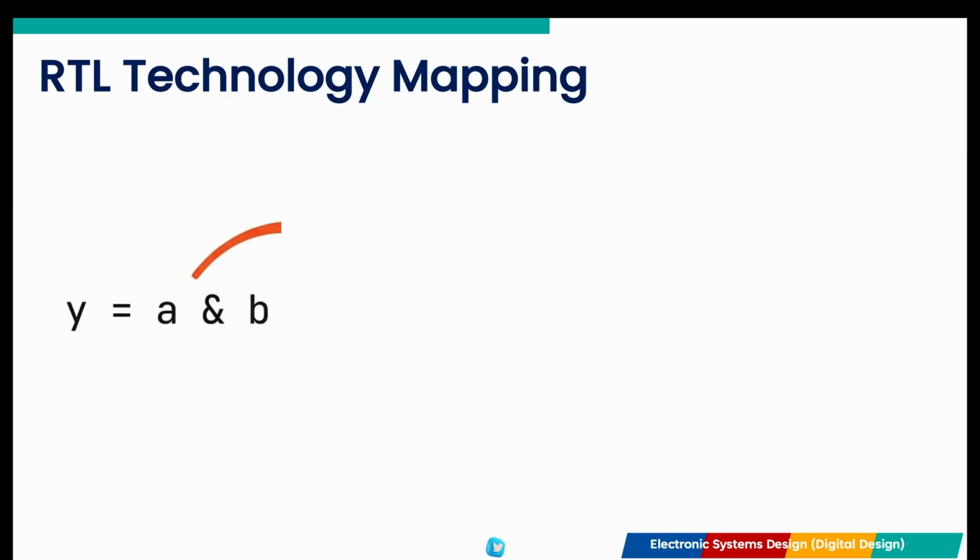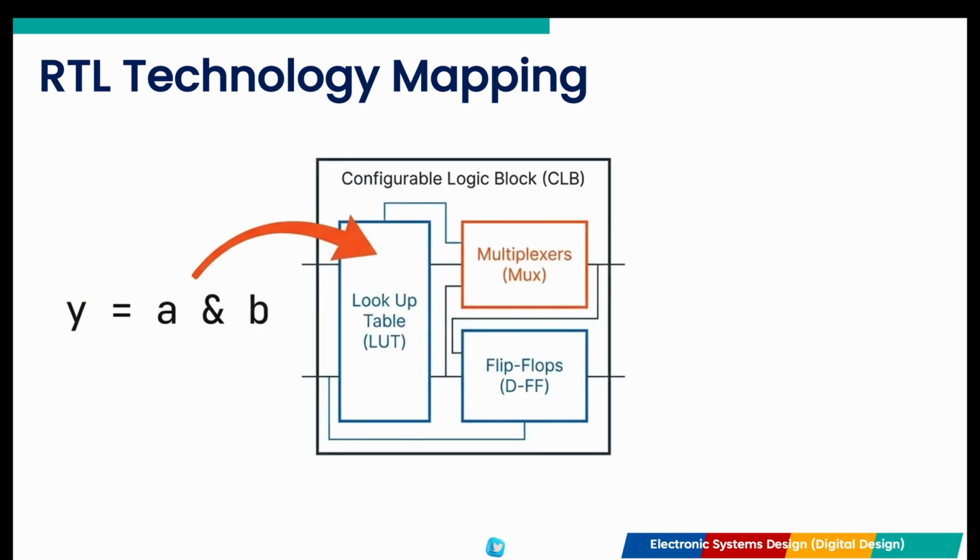Now that the logic is as small as possible, we move into technology mapping. A generic AND gate doesn't exist on an FPGA. Instead, FPGAs use lookup tables. During mapping, the tool groups your optimized logic into these lookup tables. A single 6-input lookup table can replace dozens of individual gates. The goal here is to minimize the number of levels or hops between registers. Fewer levels means the signal travels faster, allowing you to increase your system's clock speed.